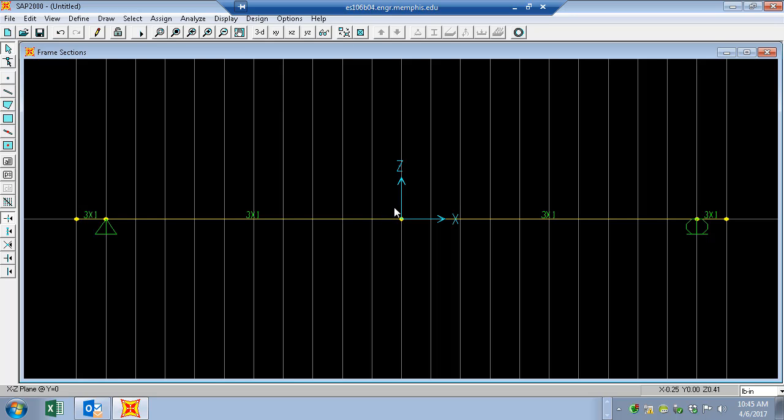inches. Okay? Now the way this is going to work, let me switch back to the document camera just for a second. The way this is going to work is like this. If I look at just this element that I'm drawing right here, and just the fact that I want the distributed load over the last 3 inches, this is one way SAP2000 lets you do this. SAP2000 on an element will let you have what's called a trapezoidal load. And it gives you 4 points to define that load. So what we're going to do is consider this one of our points, and this, and then this, and then this. If you look at those purple points I drew, if you connect those, you will in effect draw the distributed loading.